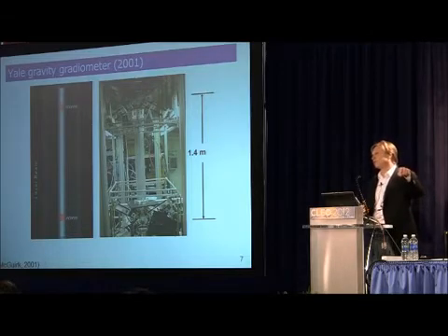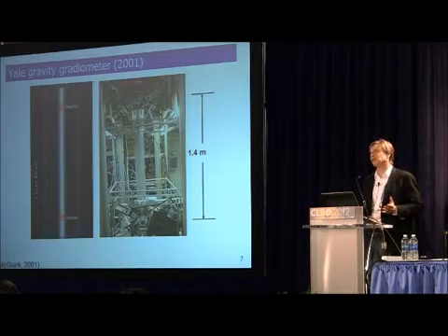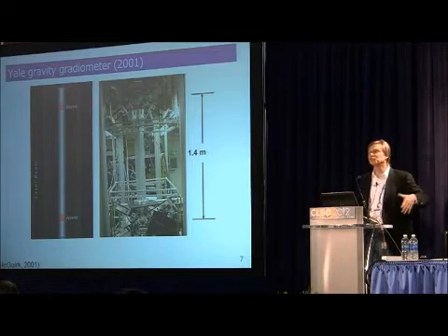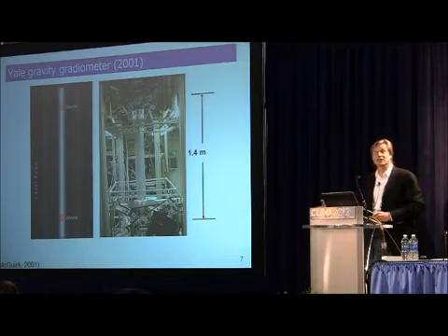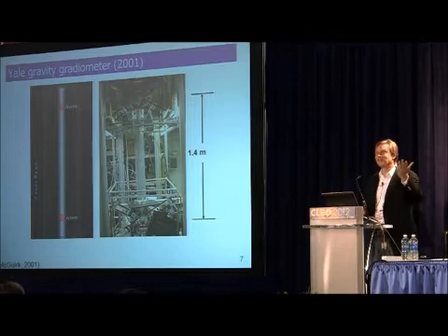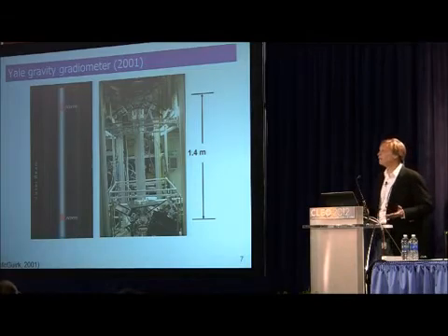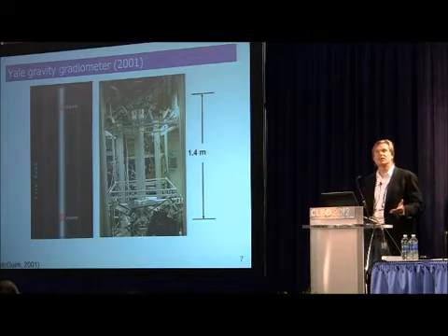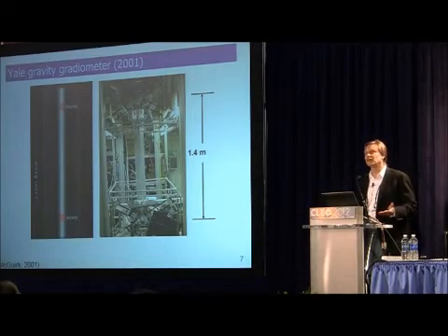If you put an accelerometer on the floor of this room and ask how much it is shaking up and down right now, you'd find it would be shaking at about 10 to the minus 4, 10 to the minus 3 of little g. You don't feel that right now, but there are hums, all those lasers and power supplies and people milling around making the floor shake. I've got an accelerometer that can do 10 to the minus 11 little g. Is it going to do me any good to have 7 orders of magnitude more sensitivity when the environmental noise is that large? No. Even in a really quiet research facility, great lab space or a semiconductor fab, you're still talking floor motion of 10 to the minus 7, 10 to the minus 8 little g. So what do you do with a 10 to the minus 11 little g accelerometer?